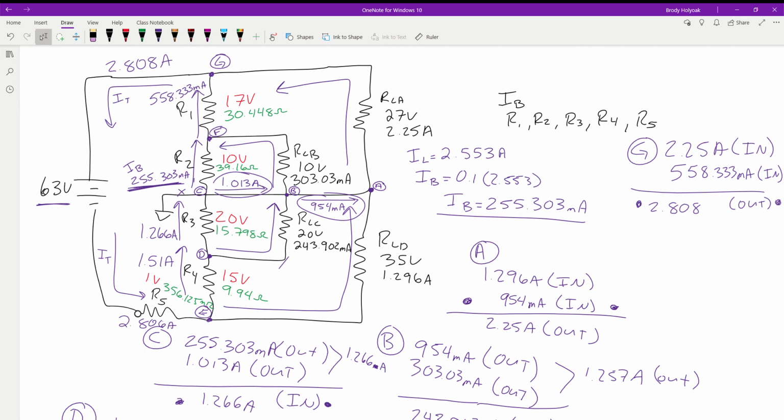We used our series laws to solve for this voltage. And then we have to switch into Kirchhoff's current law to be able to solve for the rest of this. So when I'm going through and solving one of these circuits, you look at what information do I have and what information am I missing. Right off the bat, we'll walk through this step by step. We have a connection here with 3 points. We know a value here, we know a value here, we don't know the third leg. There's a good place to start.